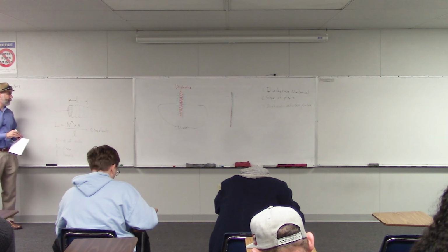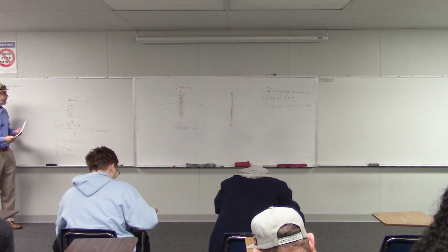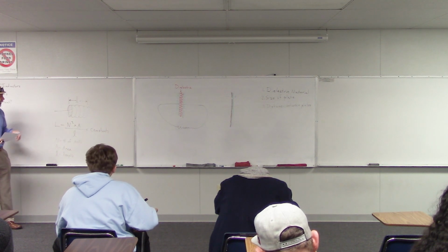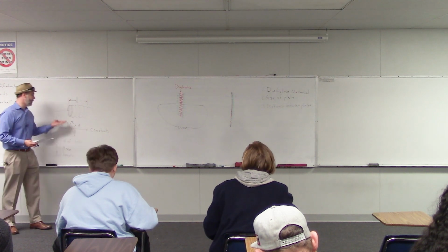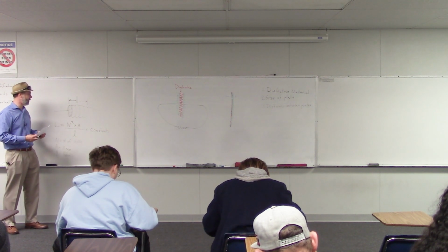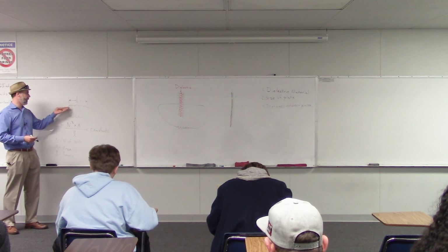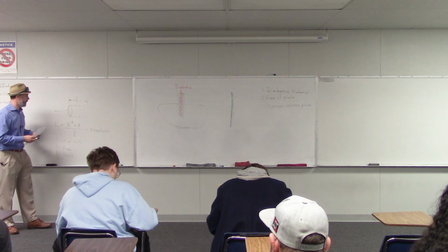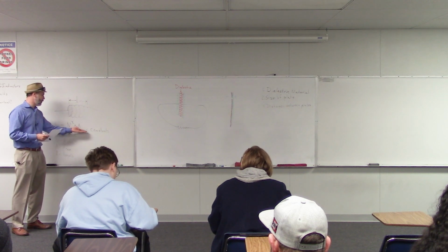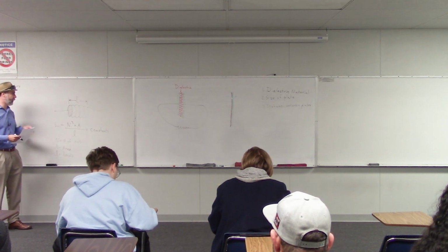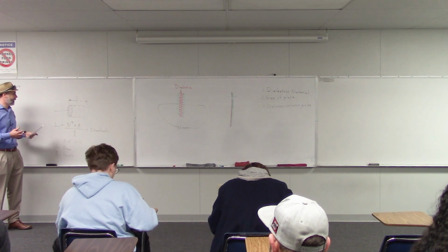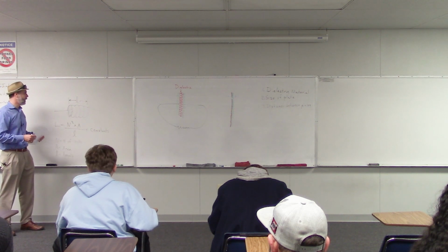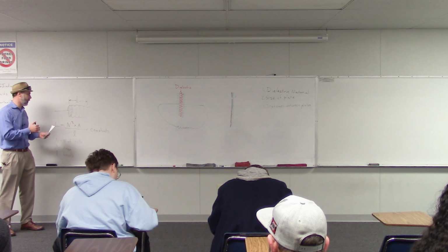So you can use that formula to calculate the inductance of an unknown coil. Now, these constants have to do with what the coil is wrapped around, and I think the width of the wire and so on. They can be a little bit finicky. So in practice, this isn't usually used to calculate the inductance of a brand new coil that you've never seen before, but it can be used to compare two different coil designs that are similar to each other.